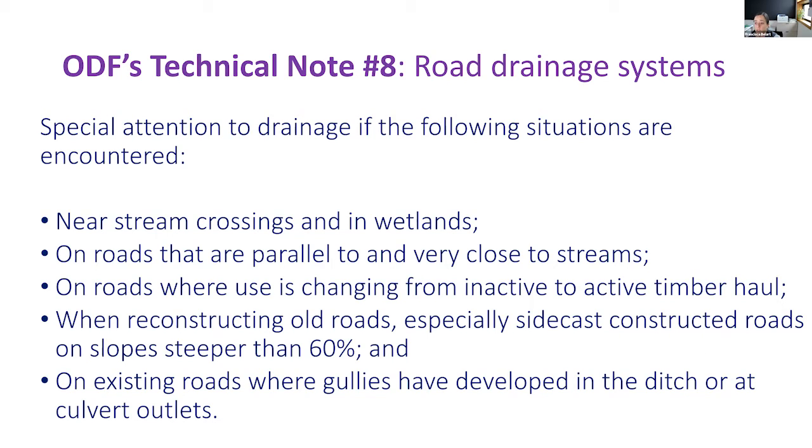paid in the following situations: near stream crossings or in wetlands, on roads that are parallel or very close to streams, on roads where the use is changing from not being used at all to active timber hauling, especially in the wintertime, when reconstructing old roads, especially side-cast constructed roads or in steep slopes that are steeper than 60%, and in existing roads where gullies have developed in the ditch or at culvert outlets.